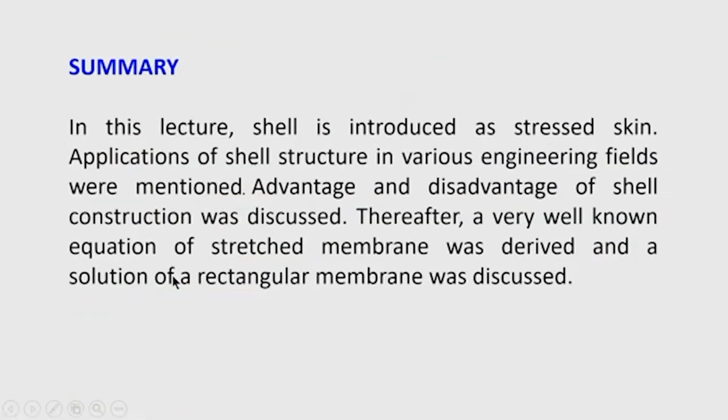Let us see what we have done in today's class. In this lecture, shell is introduced as a stress skin. Application of shell structures in various engineering fields was mentioned. Advantages and disadvantages of shell construction were discussed. Thereafter, a very well known equation of a stressed membrane was derived, and the solution for a rectangular membrane was discussed.